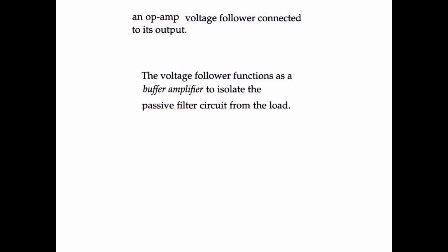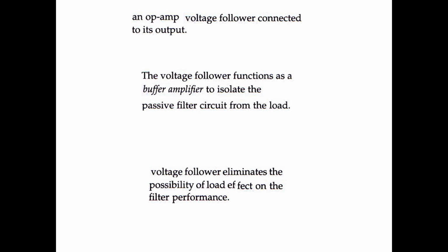An op-amp voltage follower is connected to its output. The voltage follower functions as a buffer amplifier to isolate the passive filter circuit from the load. The voltage follower eliminates the possibility of load effect on the filter performance.